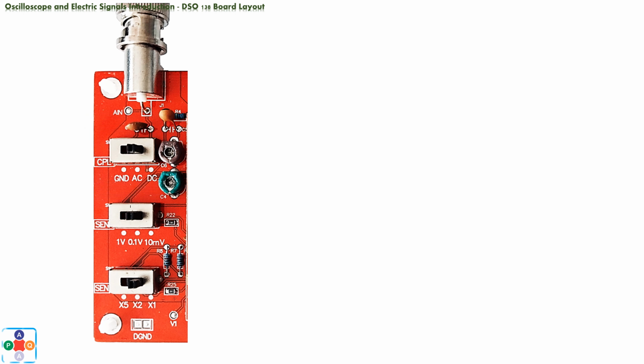In the middle, we have the SEN1 switch, which stands for sensitivity selection. It also has three positions, marked 1 volt, 0.1 volt and 10 millivolt. As the marking suggests, it is used to appropriately display the signal in regard to its input value in ratio 1:1. Now this can be a little confusing, so let's make it more clear. If you anticipate the input signal to have a point-to-point value in the volts range, let's say from 1 to 5 volt, you will operate the oscilloscope in this mode of work. The above-mentioned internal square generator produces a signal that has a 3.3 volt point-to-point value, so when you are calibrating your device, to get the best signal display you will choose this mode.